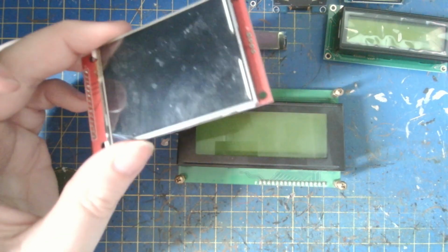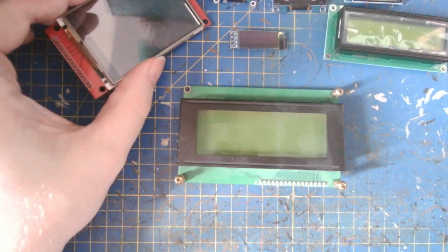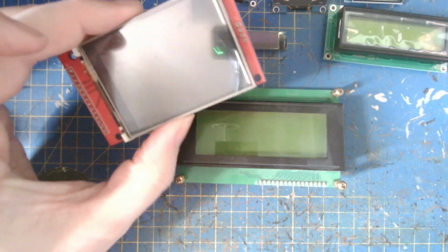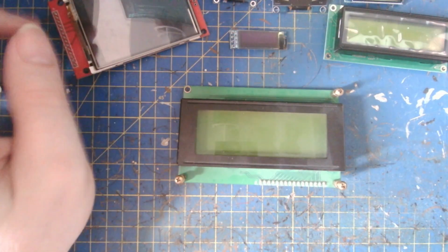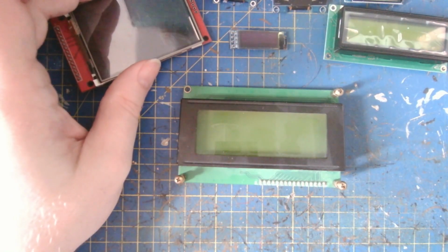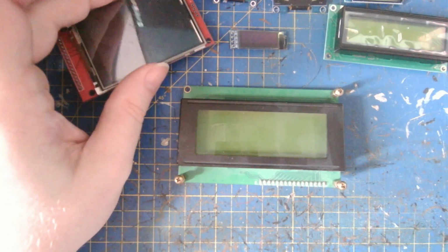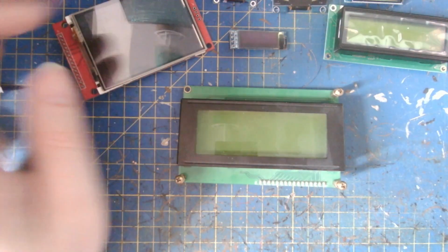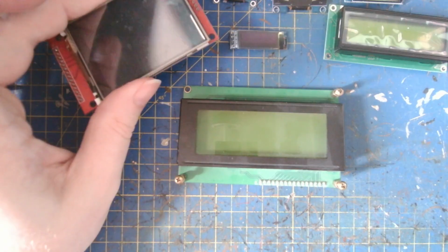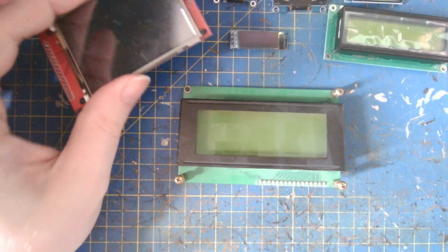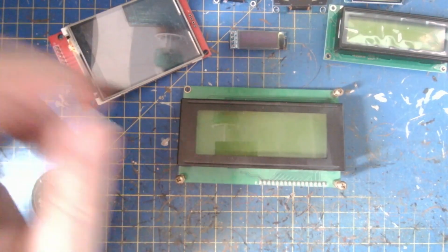That sort of thing has a controller built in. They can be quite useful. Some of them have some quite nice interface libraries built in for drawing buttons and things like that. I've used those before in industrial control settings. They tend to be the most expensive, but in some ways they're the most useful because you can get them to do quite a lot, and they'll talk back and they can be quite easy to use. Basically, using one of those, you're offloading all of the hassle of driving the screen to the screen itself, as long as you can work with the library it's got quite well.